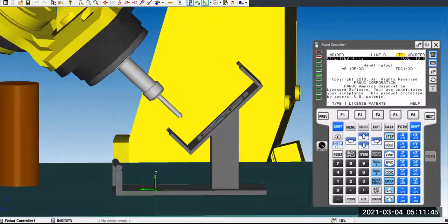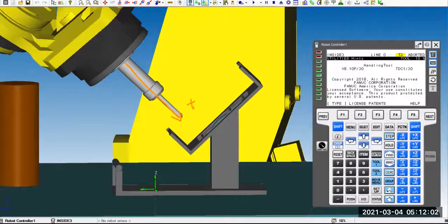With the tool frame setup, it has a very special character: the Z direction always points outward from the default. If you don't change anything from the default, this direction will be positive Z. That means if you want to get closer to the slope, you just need to go in the positive Z direction. Negative Z will be the opposite way. Again, this is a default. There's one way you can change it, but we'll talk about that in a different video.